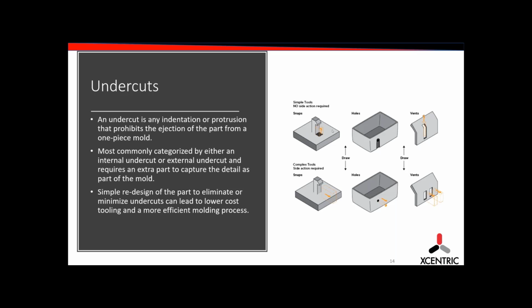forming the part. So I see a lot of extreme thicknesses that work for 3D printing but wouldn't work for injection molding, and then undercuts. The whole geometry may be undercut. With 3D printing, you can almost form a part within a part. Going to injection molding, we want to make sure that we have everything open to the line of draw. And again, your nominal wall thickness is thin with respect to what material you're selecting, and your undercuts are mitigated as much as possible.